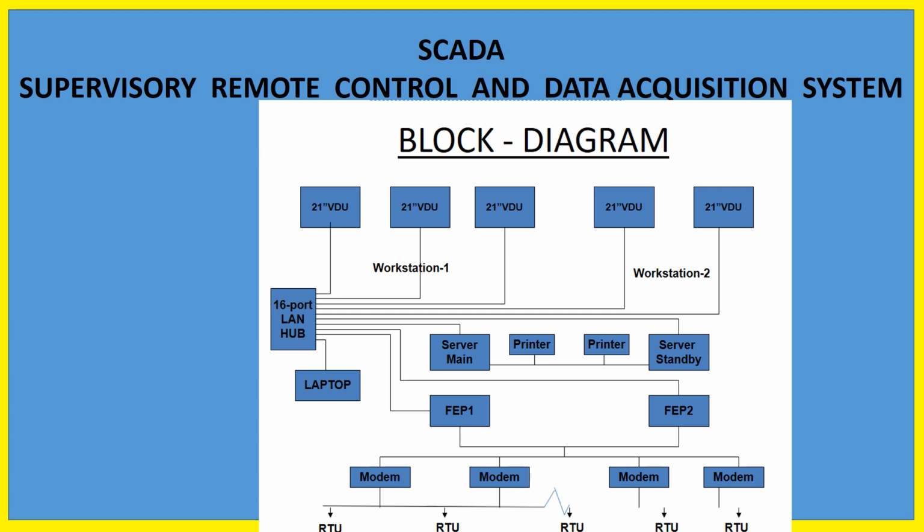The switch, like interrupter and circuit breaker, will be closed or opened, and also with the indications: whether overhead supply is there or not, PT (potential transformer) indication, battery voltage, BM status, CB status open or close, transformer status, any CB relay trip indication, power failure indication, AC failure indication, and also if a maloperation has happened, it will indicate that.